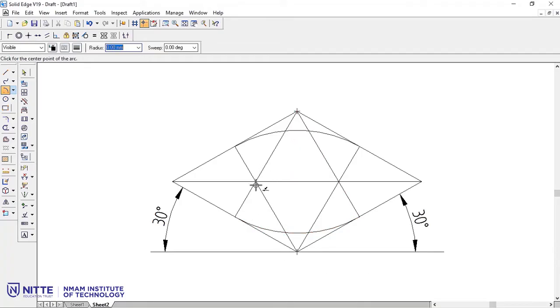Now see for the intersection mark over here, this as the radius, cut an arc. Now sometimes what happens is you cannot go in the anti-clockwise direction, so you can try it out in the clockwise direction also. So from here complete the arc, and by taking this as the intersection mark, complete the arc.